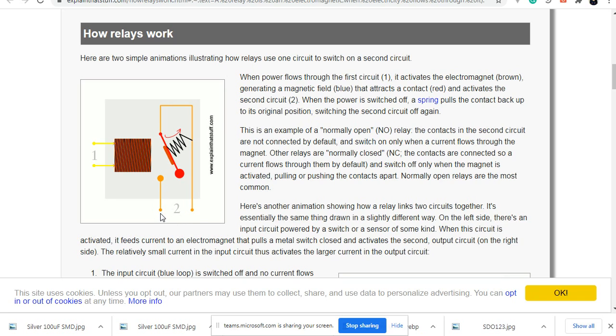But this is going to be connected with your device, meaning that this point where my cursor is at present is called normally open. Normally here means that when the device is non-energized, which means it is not given any DC 5 volts or whatever the voltage of the coil is. So when this is given a 5 volt signal, then it will close. Previously this contact point is open when it is not energized, so this is called a normally open contact point.